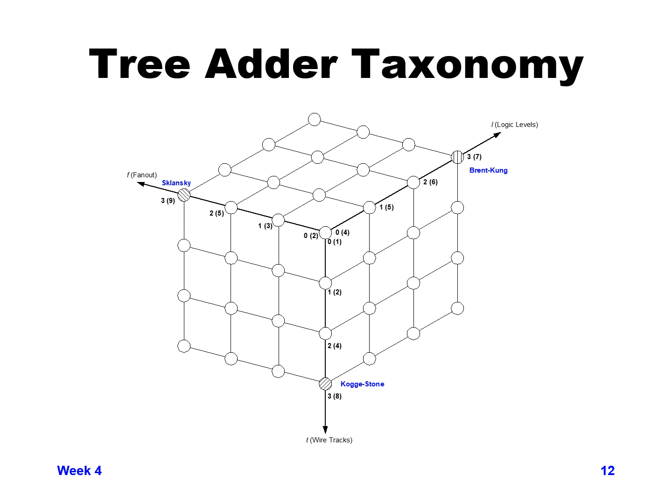The number of logic levels for the Brent-Kung design is 7, which is the base capital L of 4 plus lowercase l of 3. So 4 plus 3 is 7. That's the total number of logic levels.